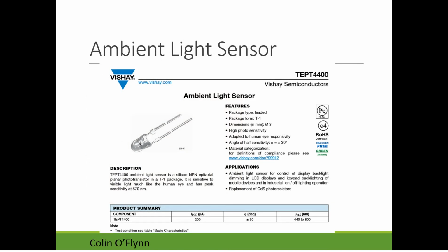What you have in your kits is this ambient light sensor. This little guy can do up to about 1 kilohertz, so you can detect a modulated signal. Again, on Monday you'll see more on that. And this is a phototransistor-based light detector, and you could think of it a bit like a changing resistance value with light. What it really is, is a changing collector current.